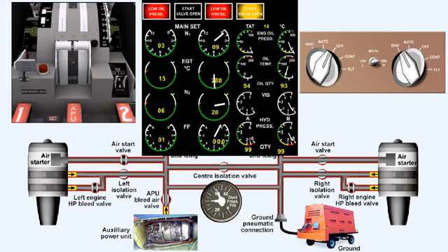It's really only possible to determine that a hot start is happening by comparing its indications to those of a normal start. The EGT may initially rise as normal, but then a rapid rise towards the engine's EGT limit caused by a hot start will become apparent a few seconds after light-up. In many cases, the only chance of stopping the temperature limit being exceeded lies in having the ability to switch off that engine's fuel supply as quickly as possible. Waiting for instructions or discussing the indications will almost certainly cost you or your company the price of a new engine. Hence the advice to keep your hand on the fuel supply control.